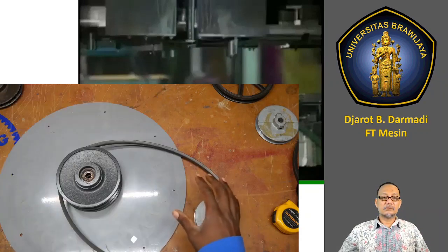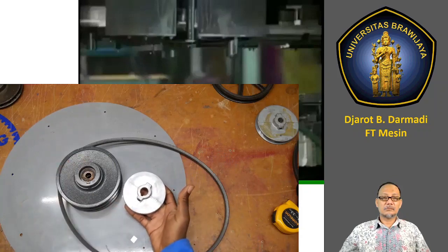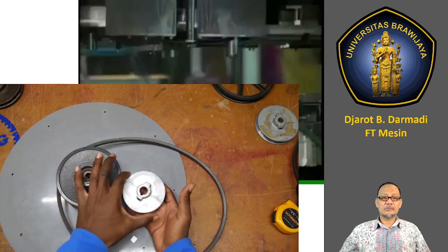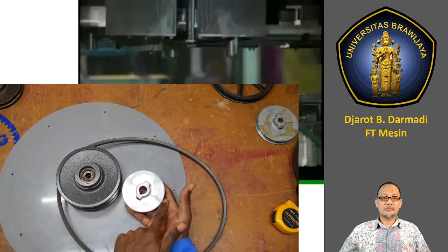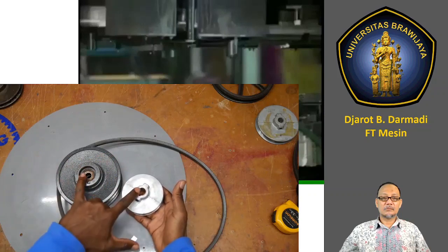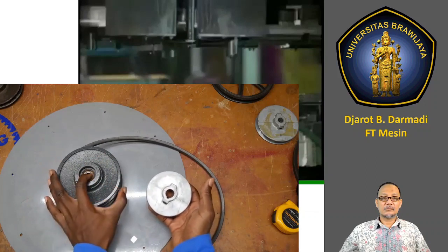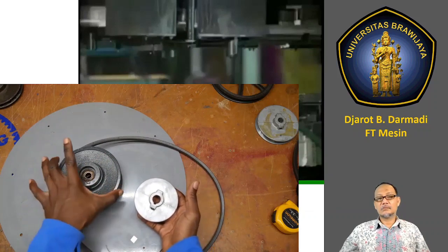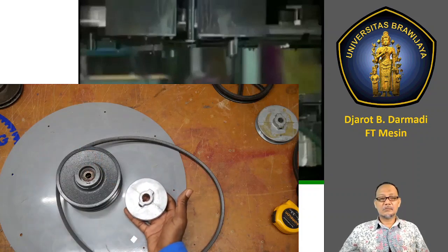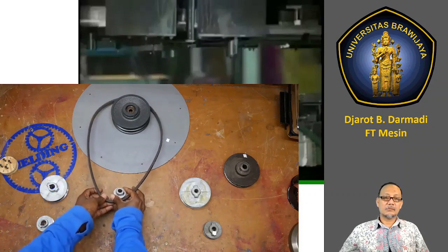and that's going to reduce the life of your belt. According to my Shigley's book, you don't want to go more than 3 times the sum of the 2 diameters. So you would add the 2 diameters together. This one's about 5 inches, and we'll say this is 3. So that's 8 inches times 3 would be 24 inches, the maximum distance you'd want to have between these 2 pulleys. The minimum distance would be the diameter of one sheave. Notice that here you've got just the radius, and so you don't want to go less than the diameter of the larger sheave.